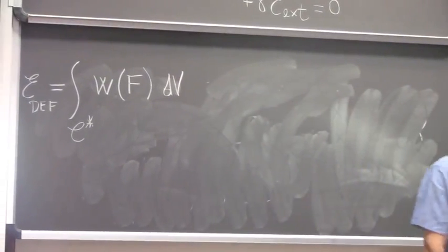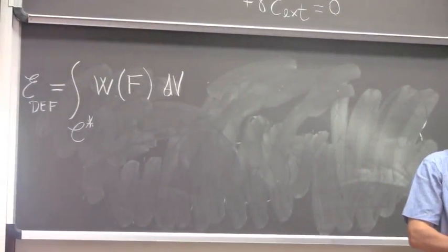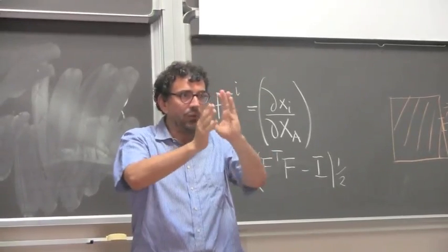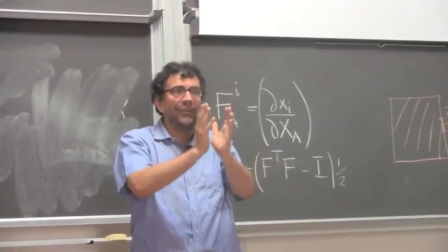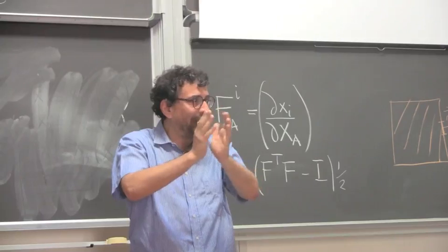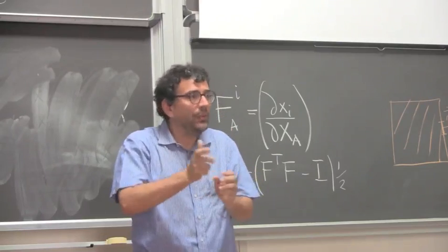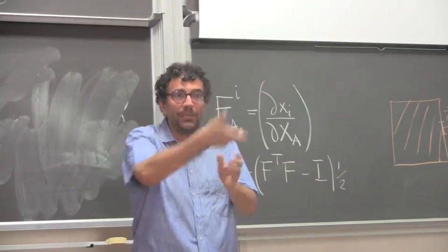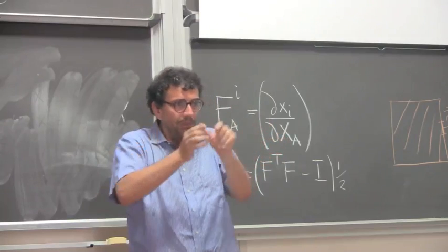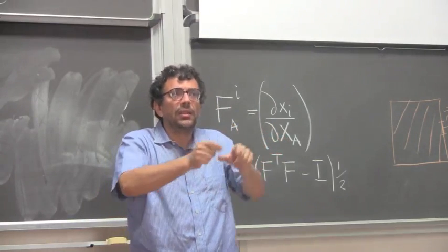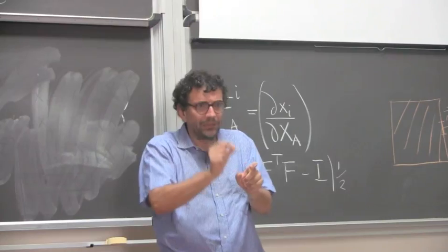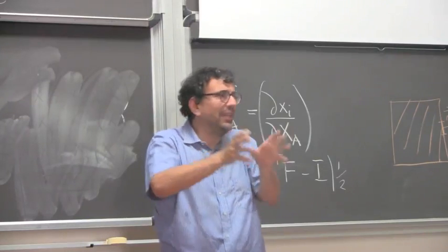You accepted yesterday the fact that I have one section and the other section, they move one with respect to the other, and you have a deformation energy related to the infinitesimal element of beam. In particular, we wrote that the energy depends on phi prime. You remember? So you have a beam, you cut it in small pieces, usually they call it beam element, and we associate to every small beam element a given energy.